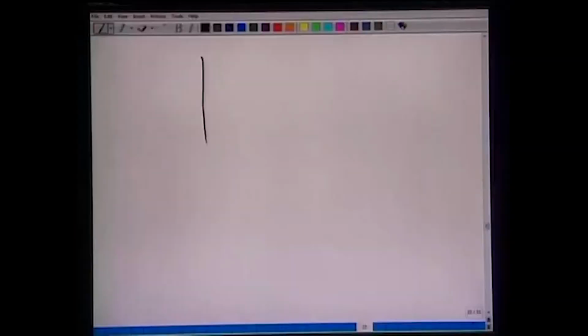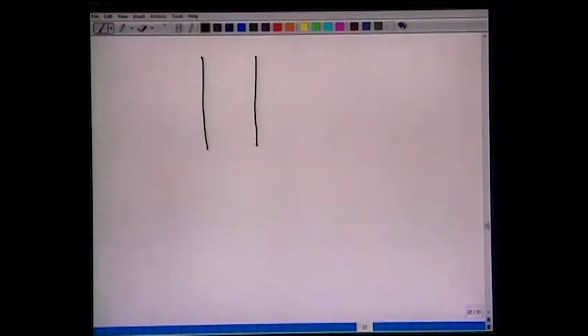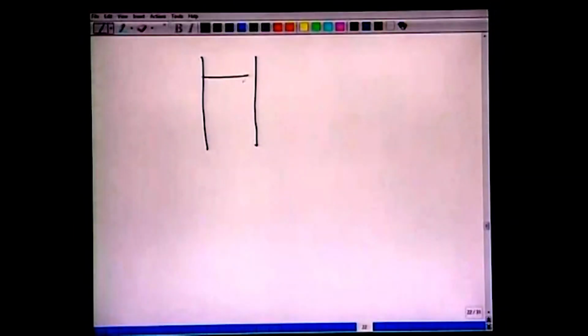In which case we have trays, they are perforated, liquid trickles from one stage to another stage, and the gas flows through these trays. Schematically, we can have the trays like this. Although it's not very common for absorptions, in distillation it's widely used, and these are perforated.